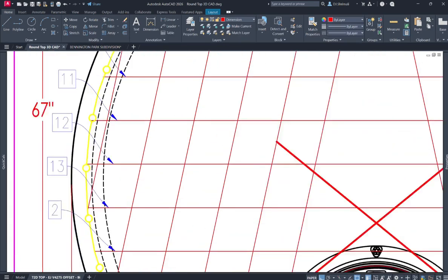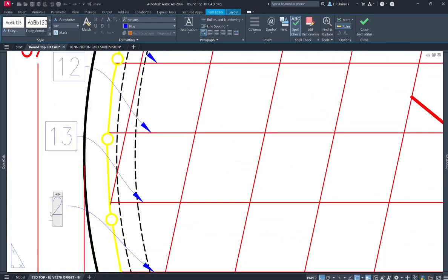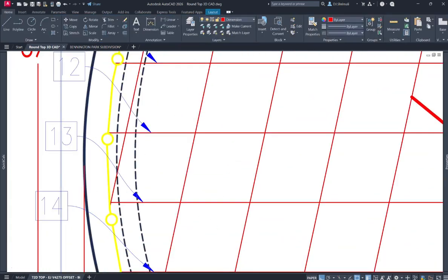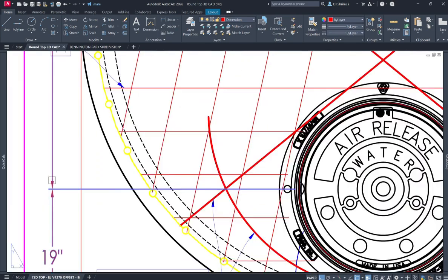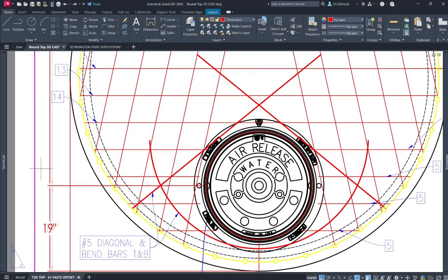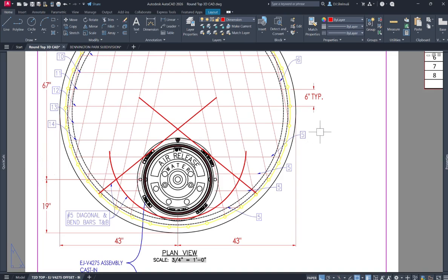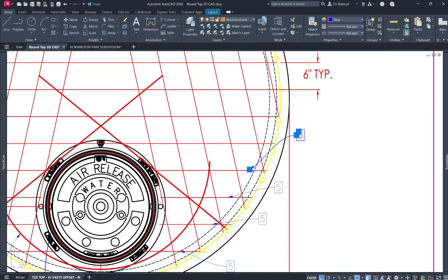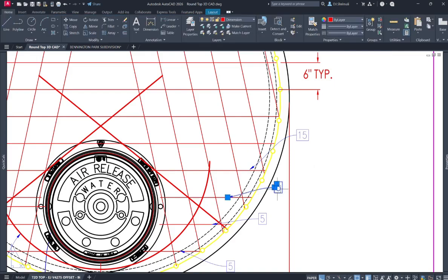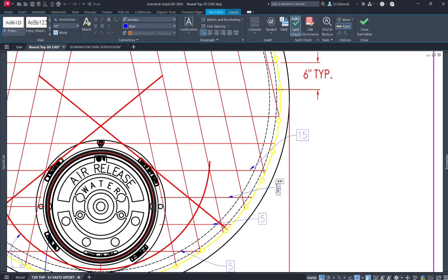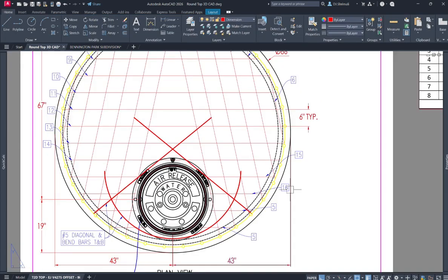And as we put the note that number 5 at 16 off center for the bottom mat, we're going to put the same note for the top mat, but we won't show that since sometimes it happens that the top mat is number 5 on 12 inches off center and the bottom mat is number 5 on 6 off center. So those are different spacing, and you cannot show both spacings in one drawing.